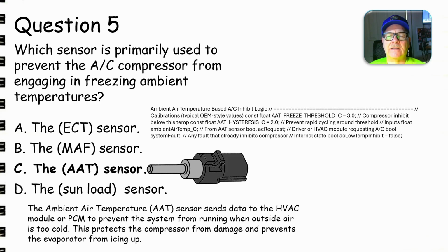And so I measured what I had a tendency to do in those days. We didn't have data stream on that particular year model of Aerostar. Ford didn't come out with data stream on any of their stuff until 1988, and it was on Continentals. Anyway, I back probed the engine coolant temperature sensor, and I noticed that thing had a skewed reading that it was sending the engine controller, and it was reading hotter than it should have been, but it wasn't completely open. You see what I'm saying? So I said, all right. So I noticed as the thing cycled off, the ECT sensor was telling the engine controller the engine was hotter than it actually was.